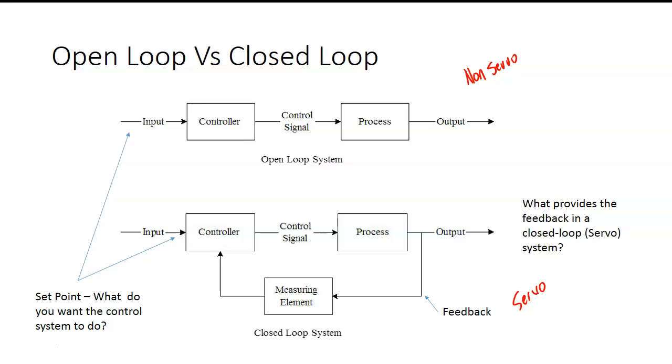In an open loop system, we tell it what to do, we take it for granted, it's done. A closed loop system means we tell it to do it and then we verify that it's done. Most of ours are going to be open loop systems. So we'll put the sensor over on the left-hand side, run it into a relay, and it's going to turn on a light.